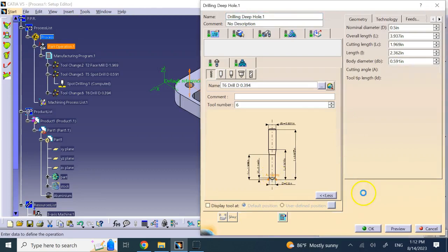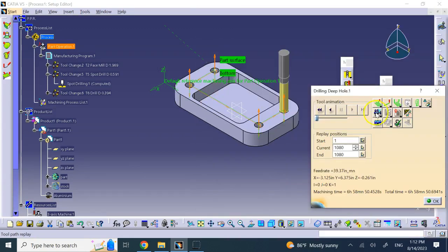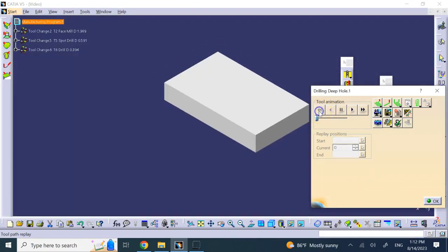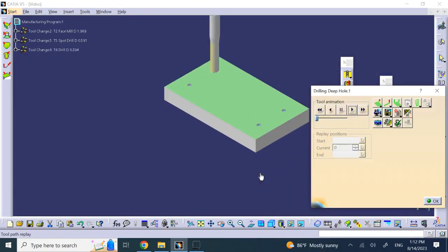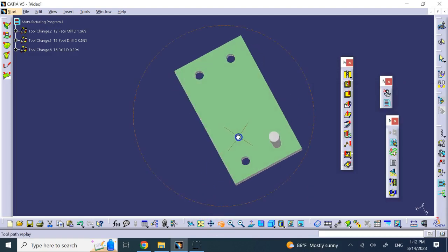Okay, so if you make that 0 and make it flat like that, and let's do it one more time, then it should be able to go all the way down. Or you need some offset from the bottom plane, so it drills all the way and makes the holes. Now, drilling, really, the tip bit is not flat. That is going to be a mill. It's not a drill if it's flat. So you see, it does the job, right?